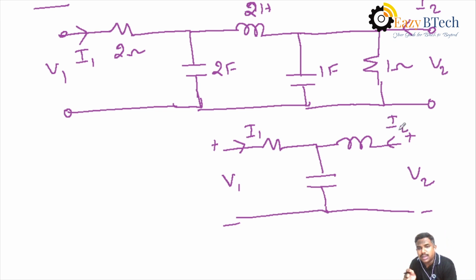Then here we know the circuit consists of RLC parameters. If the circuit has RLC parameters, how to change the given circuit? Okay, the circuit must be converted into a transformed network. What is the transformed network? That is, you have to apply Laplace transformation to the network. Then the converted network is called the transformed network.